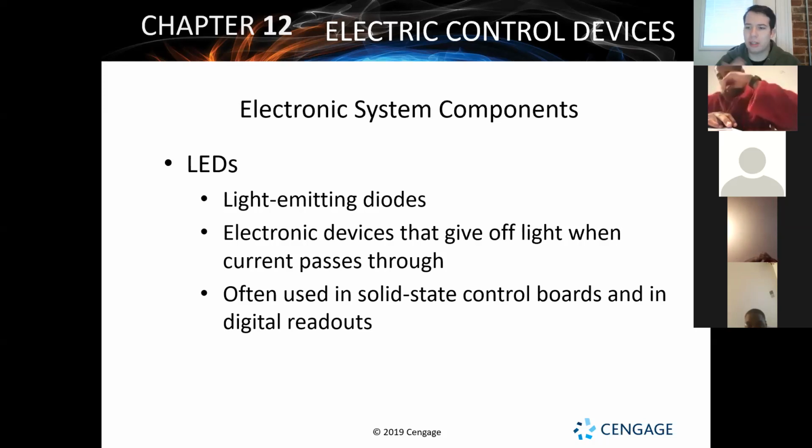Depending on the manufacturer, the typical setup is that at the indoor unit, and for modern systems also at the outdoor condensing unit, you'll have two control boards. On each control board will be a light emitting diode that will blink and give you a code.